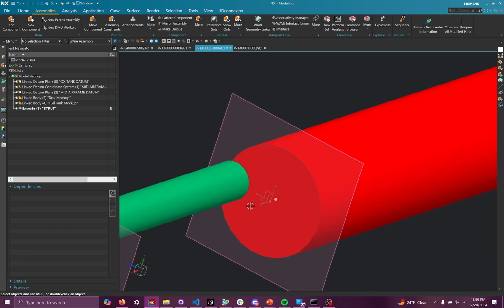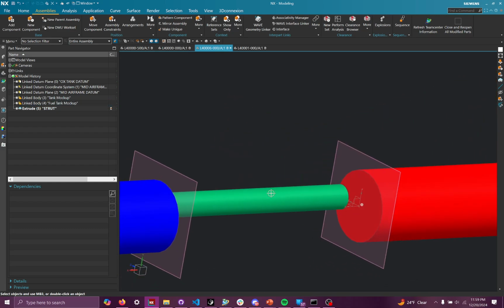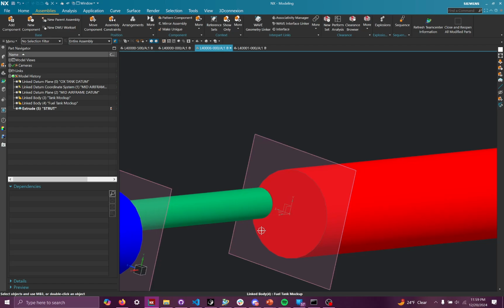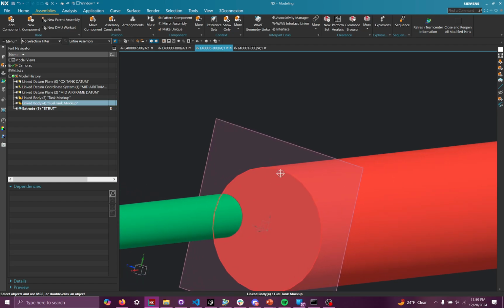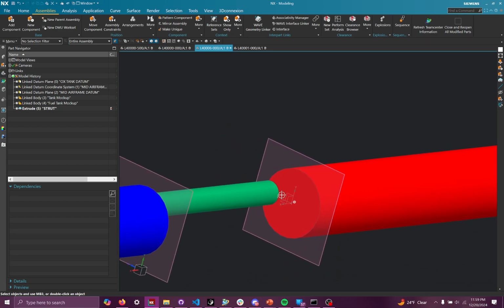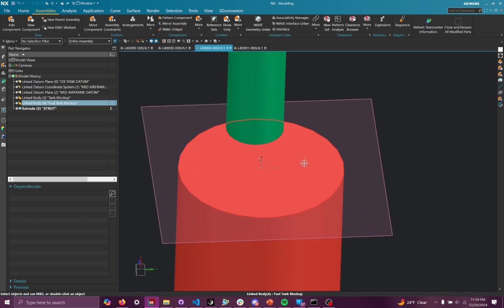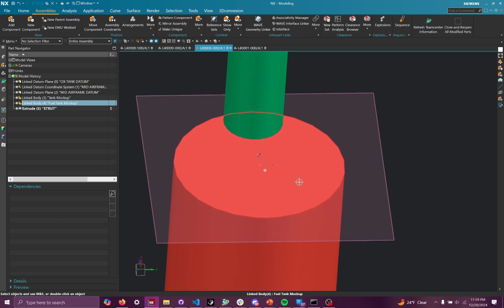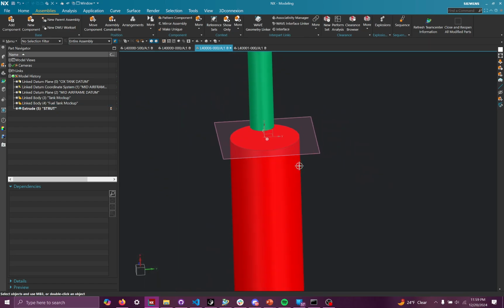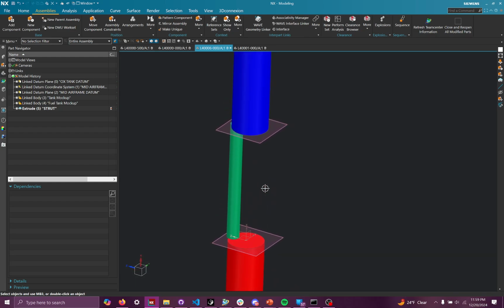You would want to be able to reference off of that strut pad, I'll call it, while you model your strut, right? Because you want to follow the same bolt pattern and have the same dimensions on your strut that you do on the tank bulkhead. So that's why you want to bring in the geometry from the tank into this file here. Yeah, so that's why we want them in there.